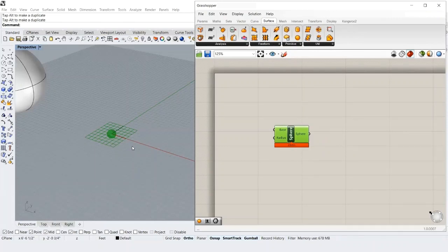That's telling us the sphere is selected in Grasshopper. So, see? The sphere on Rhino window is previewed. We can't select it. We can't move it. Actually, we can't touch it. All of our transformation of the sphere has to happen inside Grasshopper.